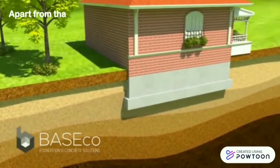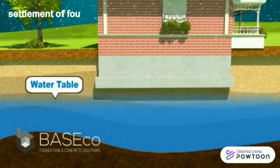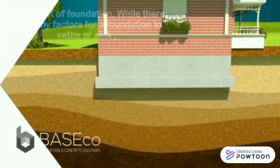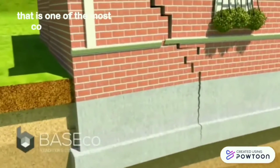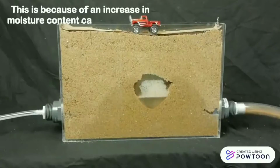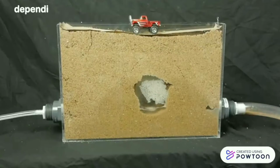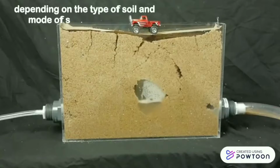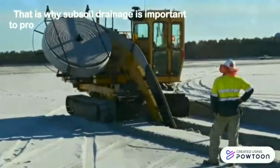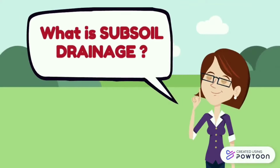Apart from that, increases in moisture levels can also lead to settlement of foundation. While there are many factors for a foundation to settle or sink, that is one of the most common factors. This is because an increase in moisture content causes a decrease in strength or stability of the soil mass, depending on the type of soil and mode of stress application. That is why subsoil drainage is important to protect your property from water damage. Now, let's see what subsoil drainage is.